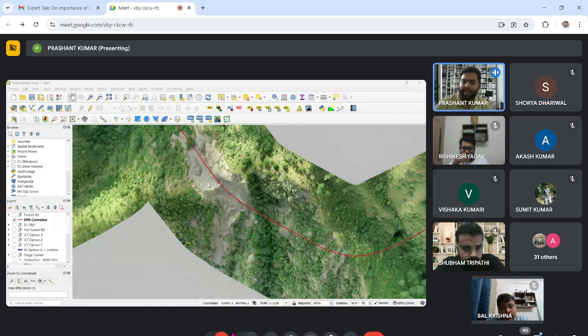Even the angle of friction of the rock, if I do the analysis, we are mostly encountering physics data. We go to RocLab, and whatever GSI value we calculate, the max we can have is around 38 degrees and somewhere around 150 kPa. It's not more than that. So that slope is not going to be stable.